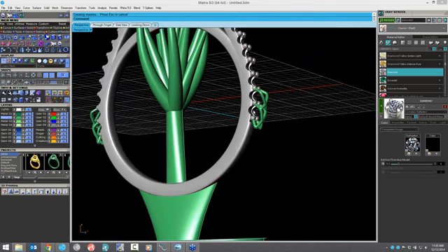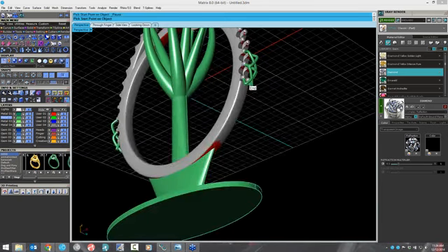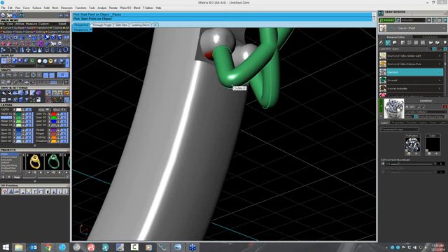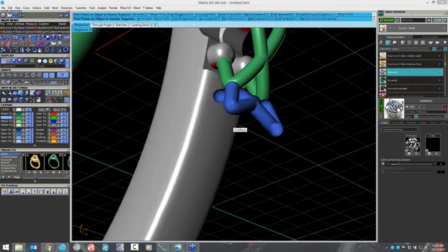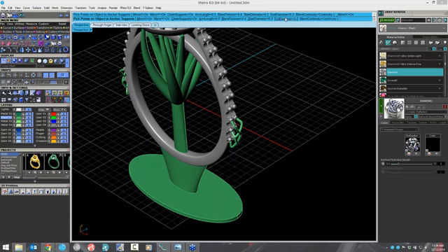Now these supports are down facing. So the last thing I'm going to do is make a support that goes down to the base. So let's zoom in here, and I'll click on the downward facing part of this. And then I'm going to send that down to the base, but it gets awful thin. So that's a little too thin to grow. So I'm going to go to the end diameter and change that to 1, and then come back, and that's a stronger support, and hit enter. So there's